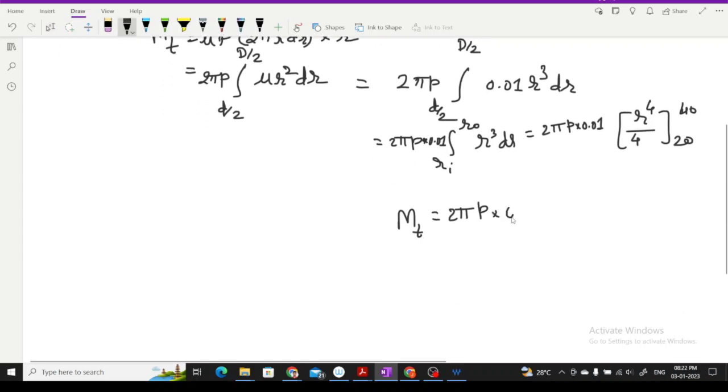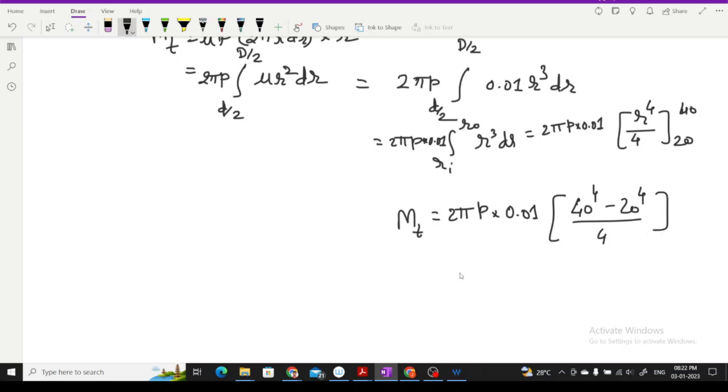So here it will be p times pi by 2 into r to the 4 by 4, and this M_T is 18.85 times 10 cubed. Is it correct? Which will give you this pressure. Yes. So this pressure will be 0.5 MPa.